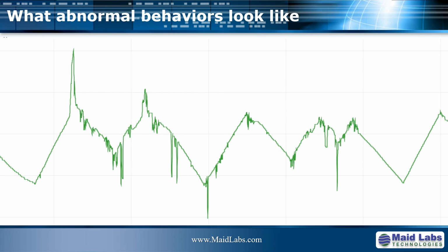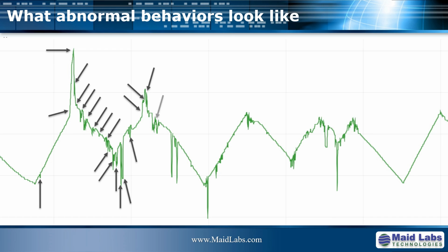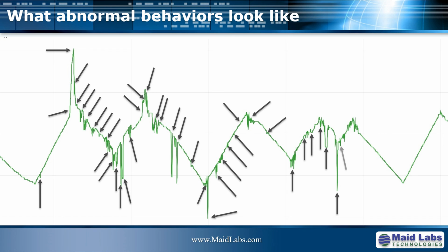When you have a defective level sensor, it looks like something like this. This came straight out of a lift station with a SCADA system, a top-notch SCADA system, that didn't discover anything abnormal in that lift station, by the way. Even if all the pumps were starting together at the same time, like every 8 seconds for hours in a row, it was not enough to create an alarm.